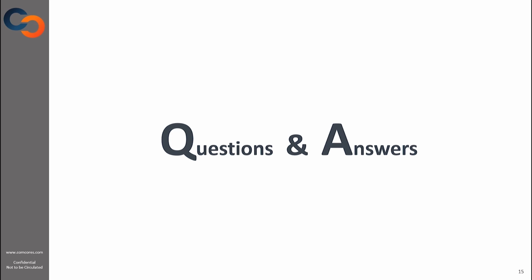And now let's move to some question and answer time, where I would like to answer some questions that came in through the chat. So first question on my list is, will JESD204D be backwards compatible with 204C? And the answer is most likely the standard will not include backwards compatibility with JESD204C.